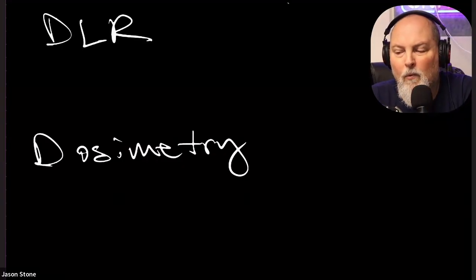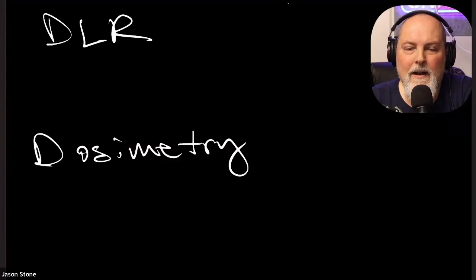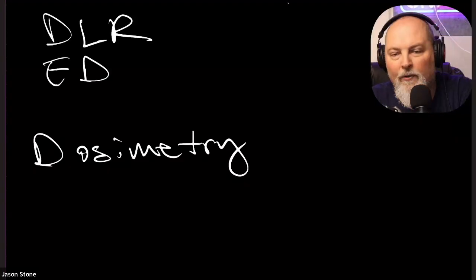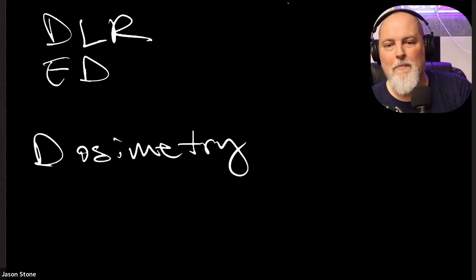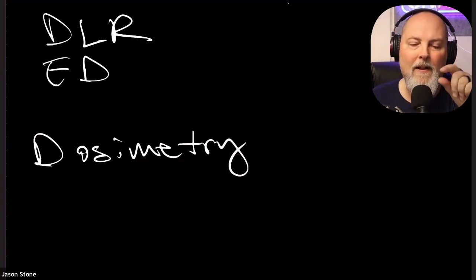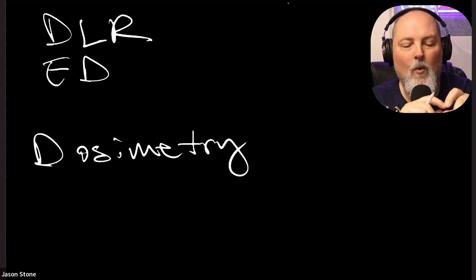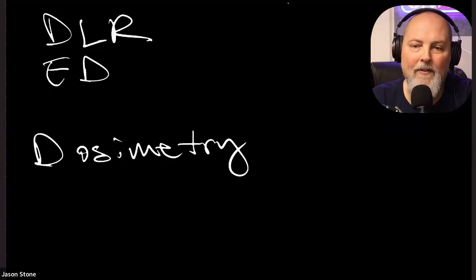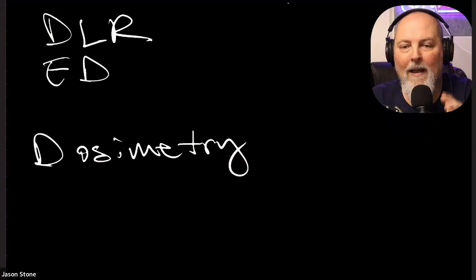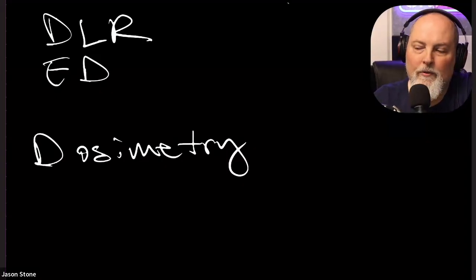Now, if I am looking to go into the reactor plant, into the radiation area, then I'll put on a second dosimeter called an ED, electronic dosimeter. It tracks live dose rate and accumulated dose. You clip it on your badge, at about chest level in front of you. It has a little LCD readout. You push a button and it tells you your dose rate, or you press a button again and it tells you your dose. So it's a continuously live count. You turn it in at the end of the day before you go home. You pick it up at work inside the radiation area, and you put it back when you leave. It tracks your dose for whatever you're doing there.